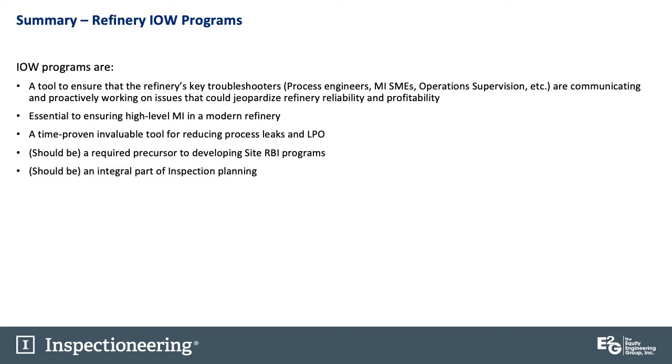IOW should be a precursor to developing site RBI programs. That's really not how it's worked in industry, but they should be. So if you haven't developed your RBI programs, I would put together an IOW program first. And IOW should be an integral part of inspection planning, which, again, was not historically the case.